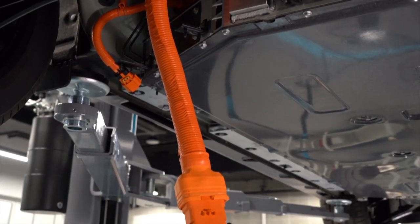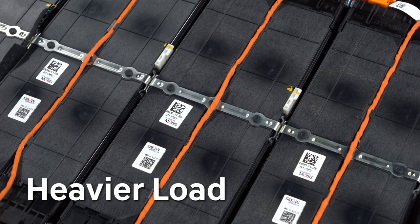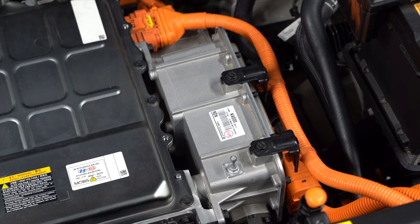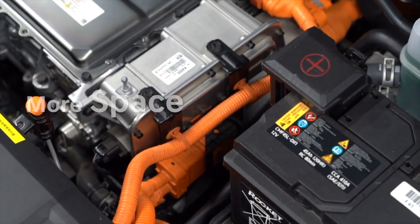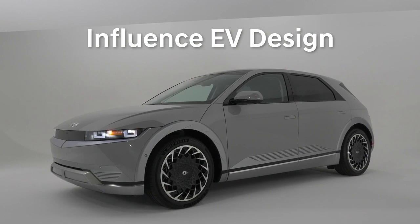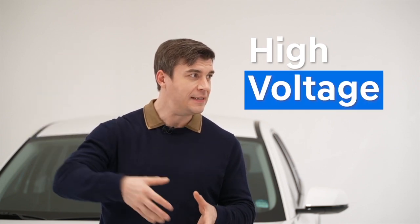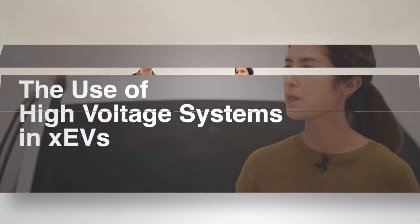Increasing the thickness of the cables in EVs means a heavier load in the vehicle. Not only is it going to take up a lot more space in the vehicle, it's going to take up a lot more weight. And when we're designing EVs, we don't want to take up space or weight if we can help it. Therefore, we use a high voltage instead of a high current. I see. So that's why we use the high voltage. Yes. Interesting.